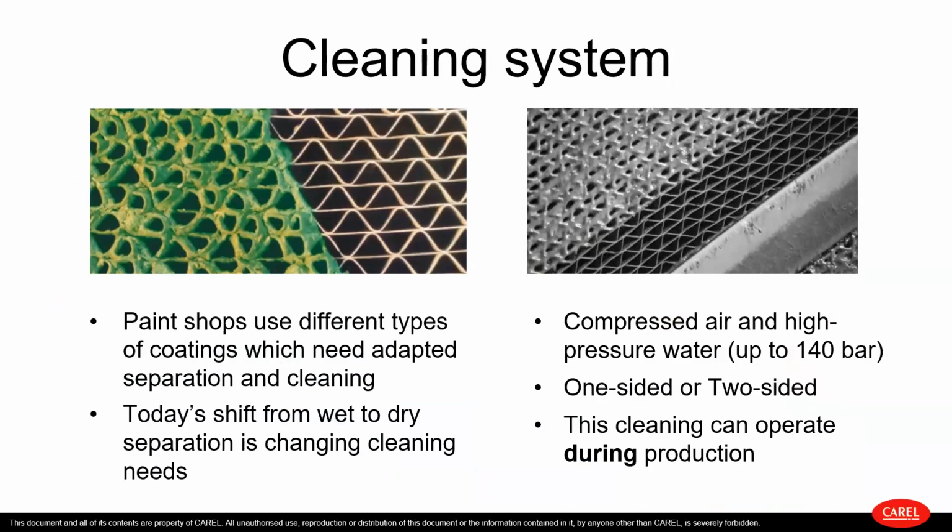Speaking about cleaning, paint is always nasty and paint will always stick on the wheel. And as you can see on those two pictures, there is a huge difference between a dirty wheel covered with paint and a cleaned wheel. This is very self-explanatory to understand that paint is harming efficiency, is harming pressure drop, and logically by all of this is increasing mechanical loads on the wheel, decreasing the lifetime. So cleaning is extremely important.